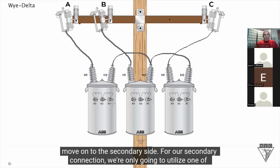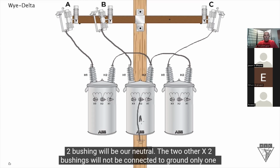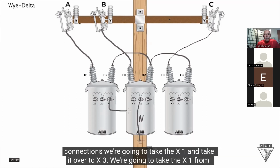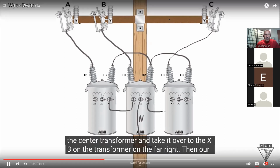For our secondary connection, we're only going to utilize one of the X2 bushings as our neutral. So we're going to take the center one down to ground, and this X2 bushing will be our neutral. The two other X2 bushings will not be connected to ground. Only one bushing is, and we've designated our center one as that neutral connection. Our other connections here: we're going to take the X1 from the center transformer and take it over to the X3. Okay, so what do we call this wire that goes in between transformers?